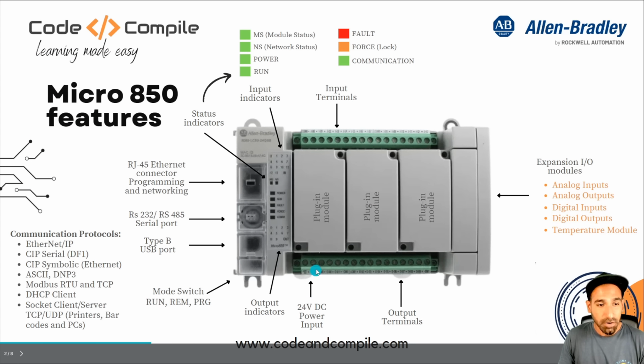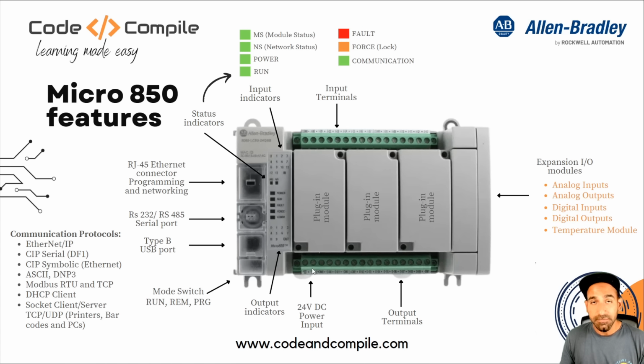24 volts DC power, it needs a DC supply. So you need to have a power supply which supplies you 24 volt DC output, which you have to give here on these terminals. So we will talk about that again when we talk about the wiring of this PLC.